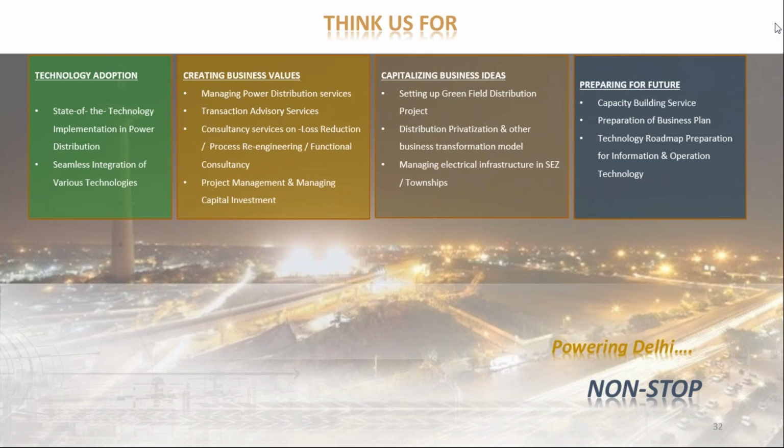That would be a part of the network planning. When you are laying your network, you have to see how long you want to take the 11 kV feeder or the LT feeder. What would be the voltage profile at the fag end? What you are saying is very correct, but we consider that as a part of our network planning. When we plan a network, we have to see there is load balancing, because unless we do that, the technical losses are not minimized.